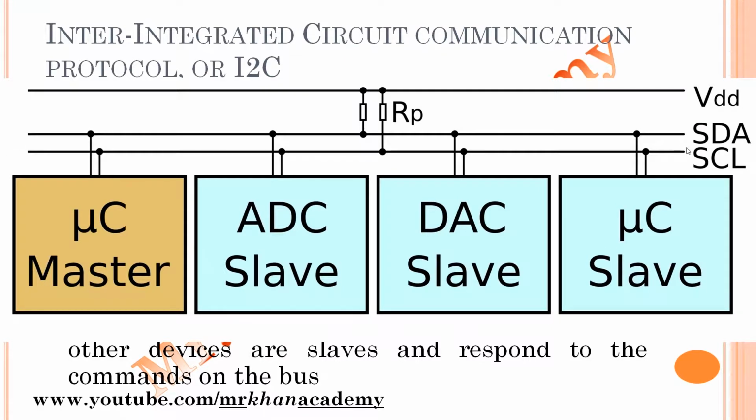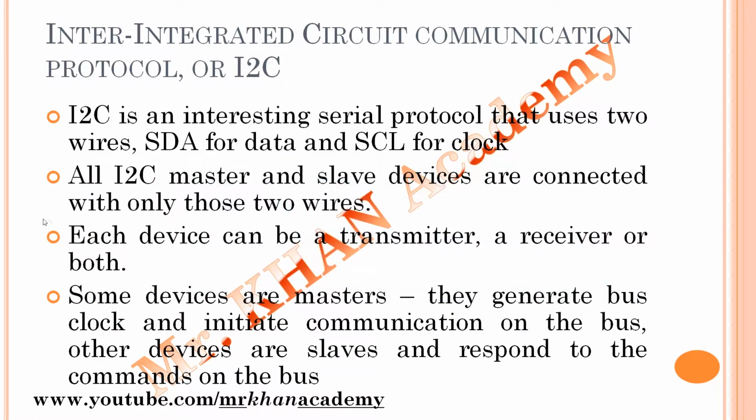As this is open drain, to get the power driven, we are connecting the positive VCC through some kind of resistance. That is what I want to explain.